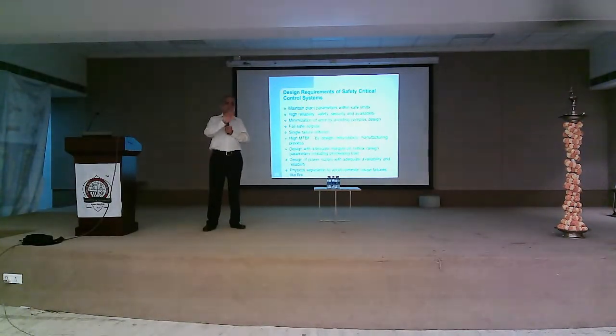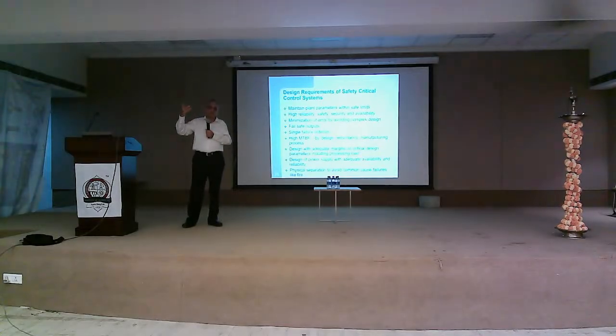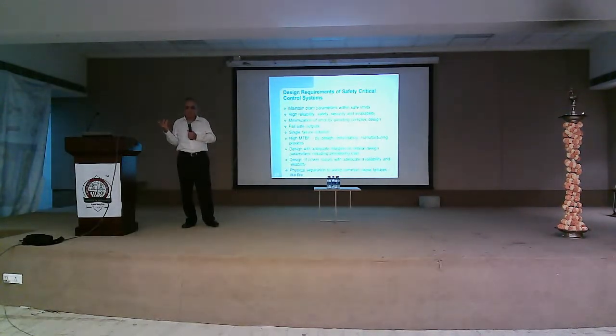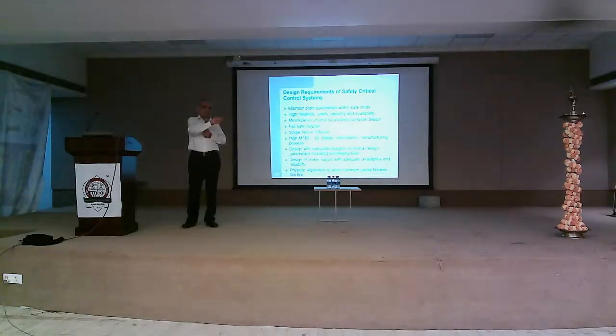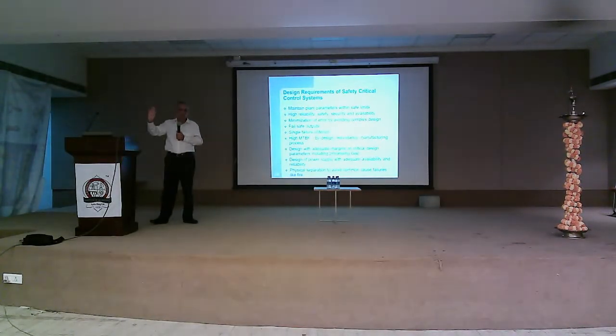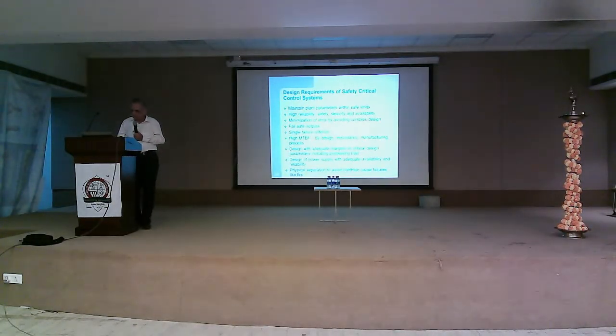There are 3 systems. Each system has got 2 power supplies, and they are also connected to 3 different sources, 3 different UPS. Suppose there are 3 UPS A, B, C. The first system will be connected to A and B, second B and C, third C and A. So that even if 1 or 2 UPS fail, or 1 or 2 power supplies fail, the system is available.